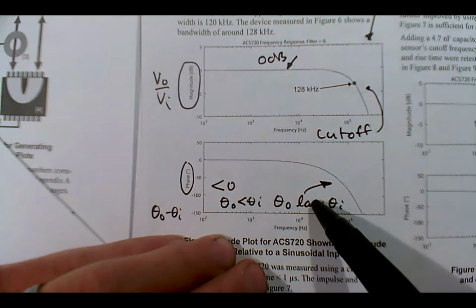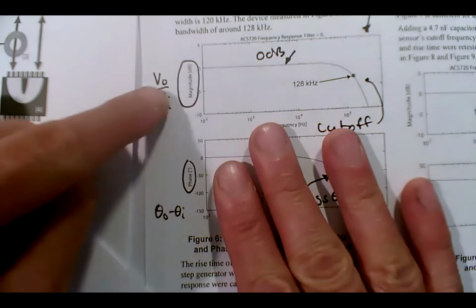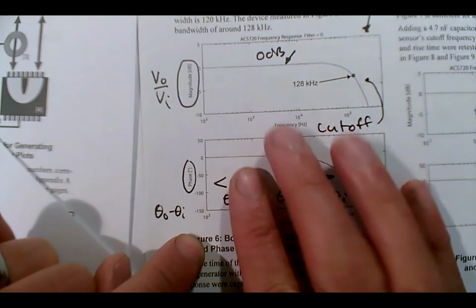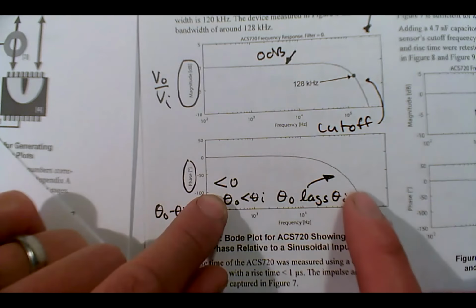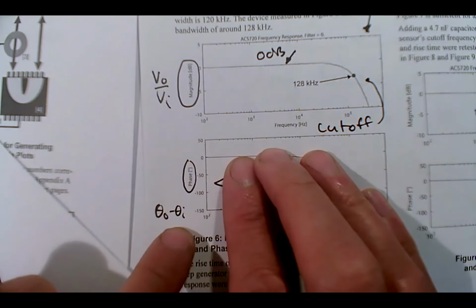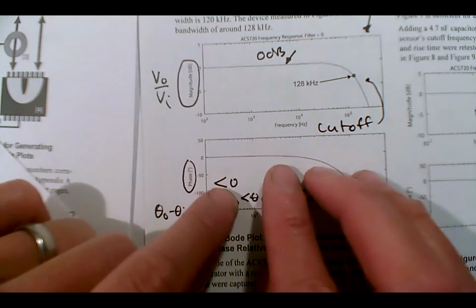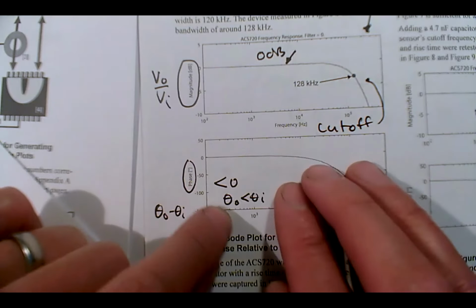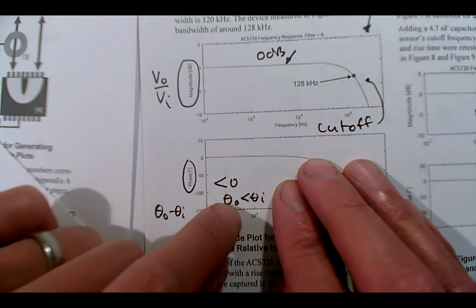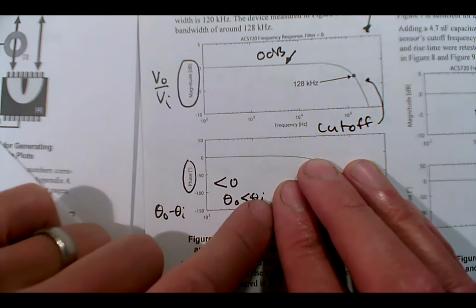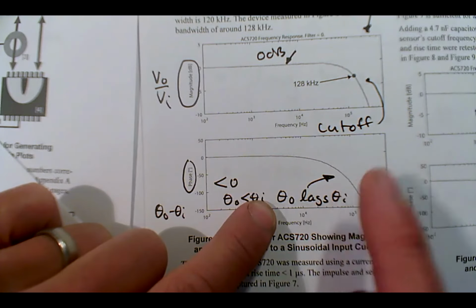This new one I'm plotting, you kind of saw in the simulation, this is a phase plot. And so the phase is actually the phase of the output minus the phase of the input. And so if your phase is negative, you can see this phase is negative. 0 degrees means there's no phase difference. Theta O minus theta I is 0. So that means these two are in phase. Makes sense, right? But as the phase becomes negative, what it means is the output is actually less than the input. And remember, we talked about the phase. If the phase becomes a smaller number relative to another one, it actually starts lagging. And so the output starts lagging the input in this case right here. And we'll see more of that later.